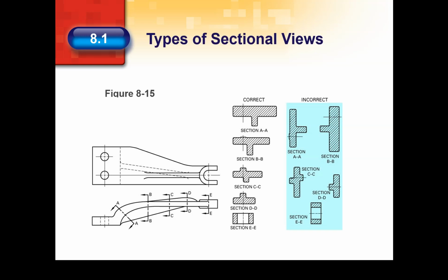When a sectional view is taken from a normal place on the view and moved somewhere else on the drawing sheet, the result is a removed section. Because the removed section is easier to understand when positioned to appear in its normal place on the view, it cannot be rotated in just any direction. See figure 8.15 for correct and incorrect ways to position removed sections.